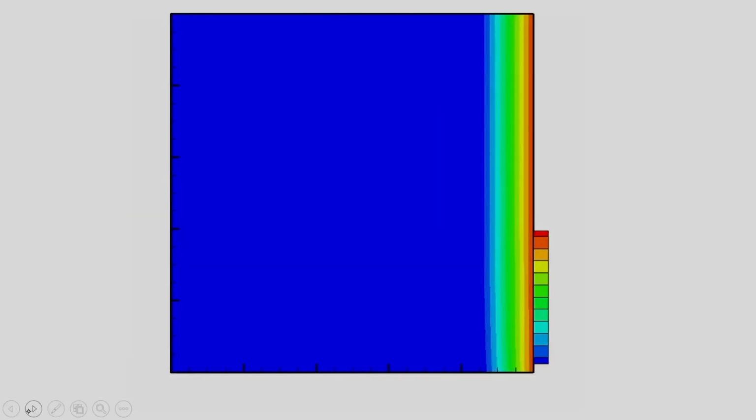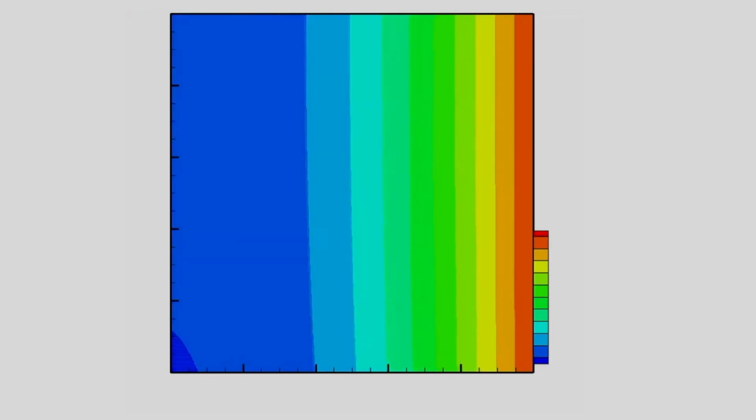Okay. So, you can see. Top and bottom walls are insulated, and left and right walls are having Dirichlet boundary conditions. So, you have 1000 Kelvin here. You can see how the heat is propagating and finally it will reach steady state. You can see how it is propagating. Okay. So, almost it has reached steady state, you can see the variation is very less.